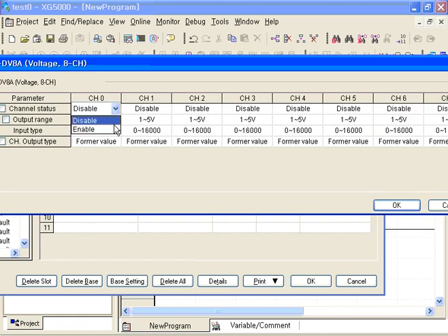Output module, the same enable. I will set the same. Output module is like this. When you apply, it gives a value to 5,000 in some special area. Then this 5,000 corresponding analog voltage would be made to the real output channel. So if I put 5,000, then 5 volts is applied to the sensor, right? 6,000, 6 volts. So that's for analog stuff.